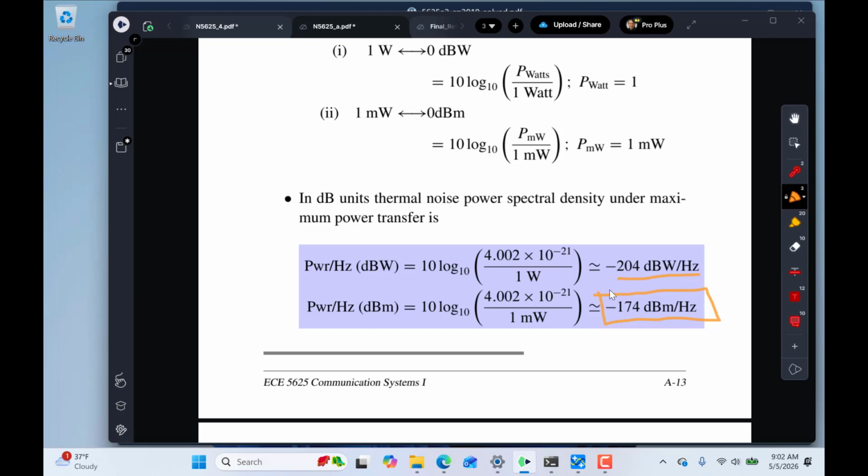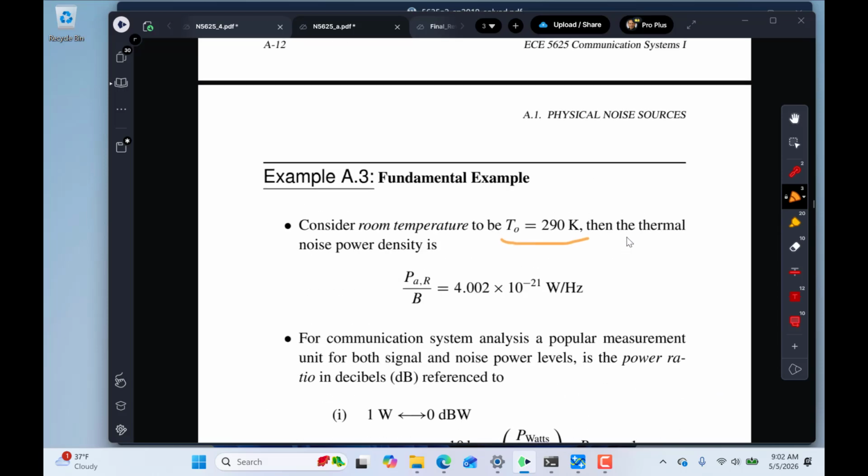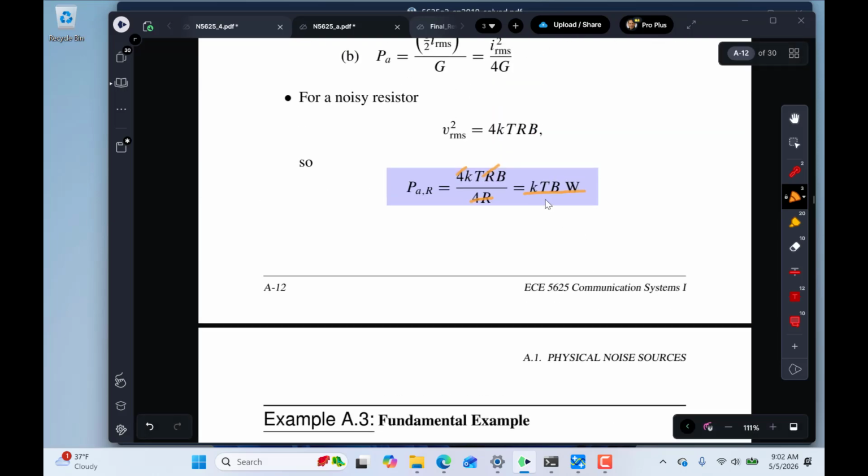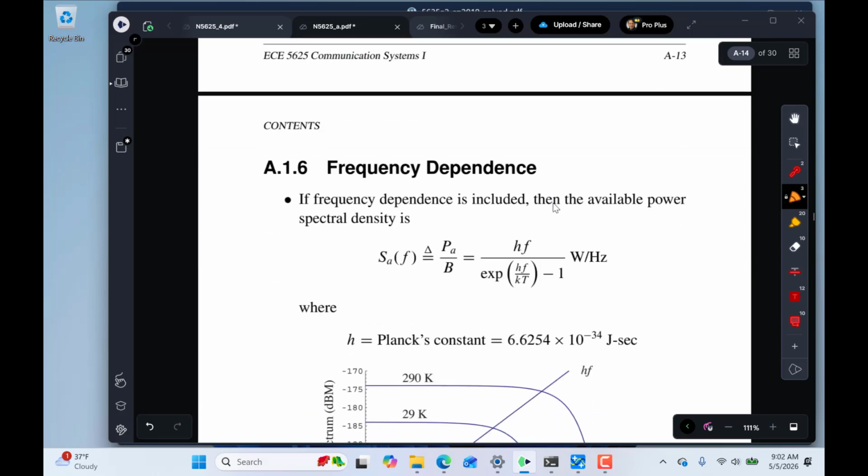I mean, a resistor, say, in a 50 ohm environment, the noise power at the input is going to be minus 174 dBm per hertz. Sound okay? Like, why that number? It's the physics, right? It's not something that you can change if you change the temperature. That's really the only thing we have available to us. We can change T, we can't change Boltzmann's constant.